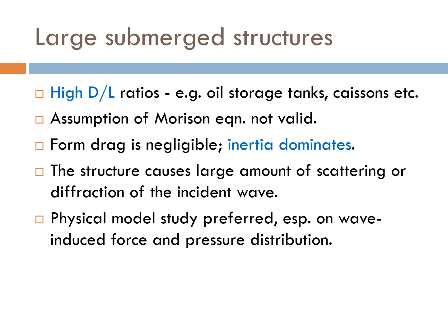Contrary to the cylindrical type structure, large submerged structures are a totally different category, whereby the D/L ratio is high. Again, D is the dimension of the structure and L is the wavelength. In this type of structure, the Morison equation is not valid.